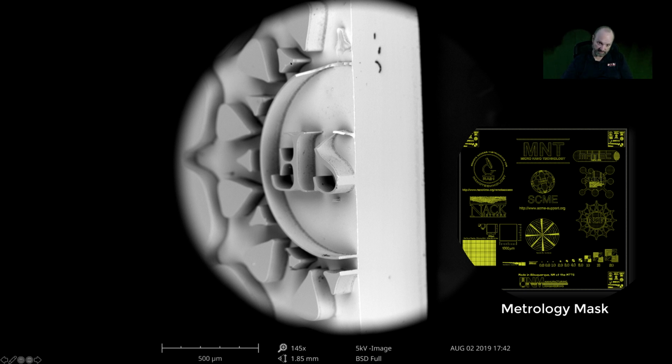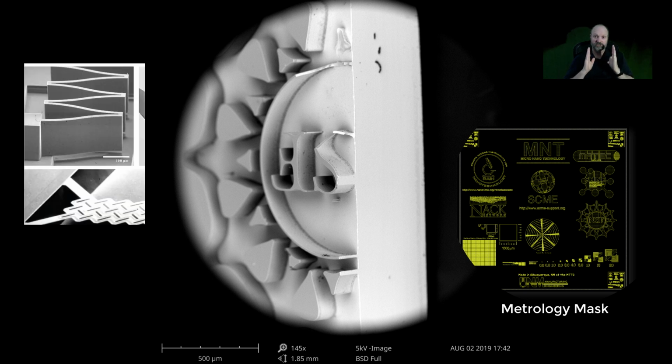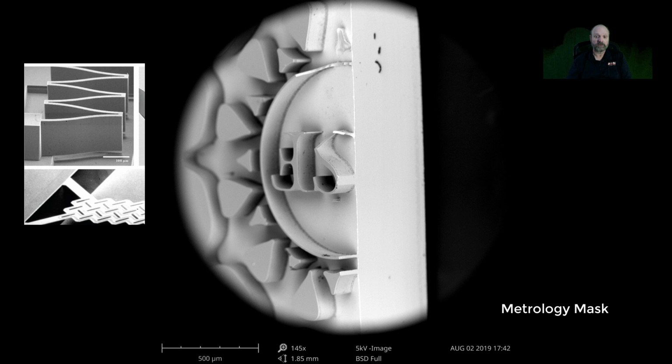So you can't see the silicon dioxide on top. That's protecting the silicon underneath. Okay, some other pictures you'll be able to see it. So it's a very thin layer that's protecting this really radical etch underneath. And it's highly directional, so you can see, you can make very tall, thin structures. So as a mechanical engineer, you can think about making very small springs that way, coiled springs perhaps, right? Anything that needs to be straight and thin, you can do that with deep reactive ion etching.